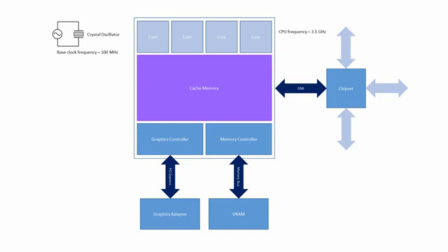Some PCs allow you to change the rate of the base clock, but getting this wrong can be disastrous. Other computer components can run at different rates to the CPU cores by dividing or multiplying the base clock frequency according to their own needs. Multipliers inside the memory controller can generate a different frequency to control the rate at which data move on the memory bus, for example. A memory bus designed to support DDR4 DRAM typically operates at a frequency of about 1.2 GHz. Some PCs allow you to overclock the DRAM as well as the processor.